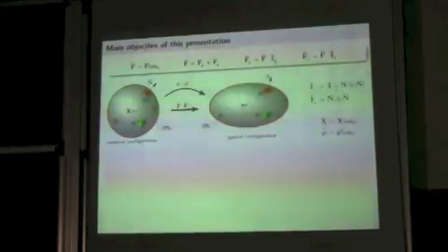What we have here is again this potato. It is in the material configuration, at time zero, shown by capital letters basically. It is deformed via a nonlinear deformation map phi to the spatial configuration at time t. And then phi hat is basically the evaluation of phi on the surface.